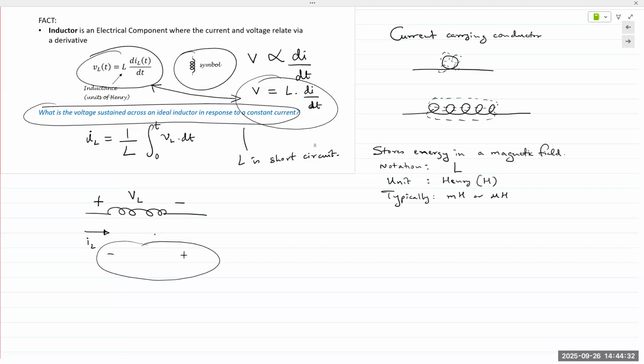Depending on the circuit, the design, and the size of the inductor and capacitor, the charging and discharging can be fast or very, very slow. But it is not instant. We can't flip a switch and have all of that energy rush into an inductor or capacitor all at once. It takes a finite amount of time. That's again physical fact, and there are mathematical equations that describe this charging and discharging. Those are known as transient analysis.